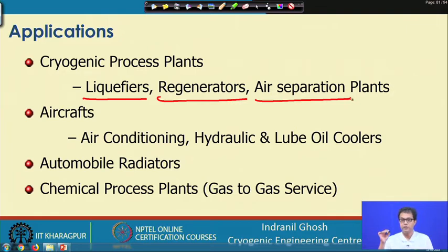We have the main heat exchangers where the air is being handled, and then we have the condenser reboiler in between the double column unit. The condenser reboiler earlier used to be a shell and tube type or tubular exchanger. These days you will find frequently that these are replaced by plate fin type heat exchangers.